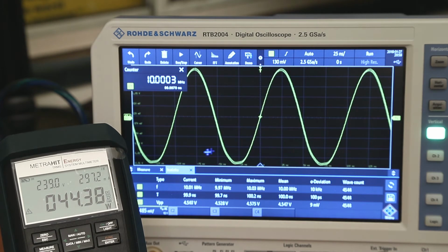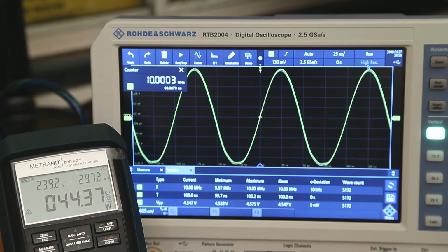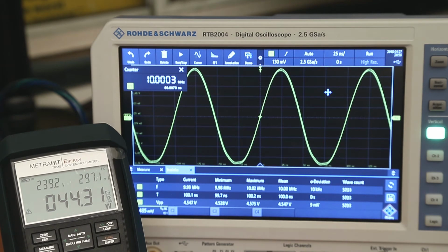but it remembers all the settings. It remembers the time base, what acquisition mode this is in, high res, etc. It remembers everything that I set it in, which is rather useful, particularly if you want to set something up and then come back to it the following day. On the Keysight I switch it off and it forgets the time base, it forgets the volts per division, etc. So I do actually like that. I think for that it's got to be left plugged in for it to do that. I haven't actually tried to power it down completely and see what happens with that.